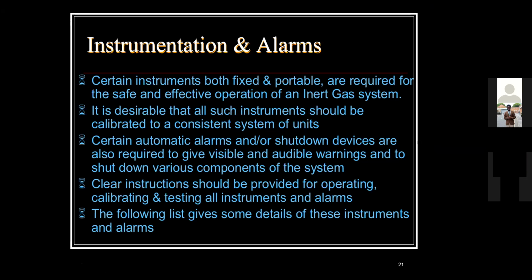It all depends. And if you are new on a different type of tanker, the way the LNG relief valve works is totally different from the way the crude oil or chemical tanker valve works. Some of them are fitted in individual tanks, while some of them are not. It all depends on whether they have a common system.